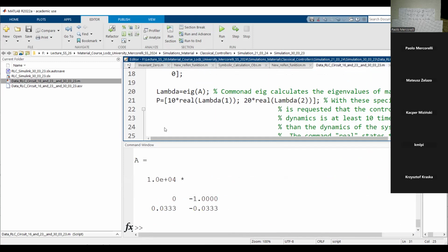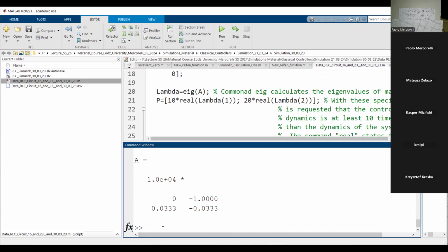As a result, here we have K, two values for K in accordance with our specification. Typically, as written in my comment, the desired lambda must be real, but it's not necessary. If I need oscillations for some reason, the eigenvalue must be complex. Very often I don't need oscillations.